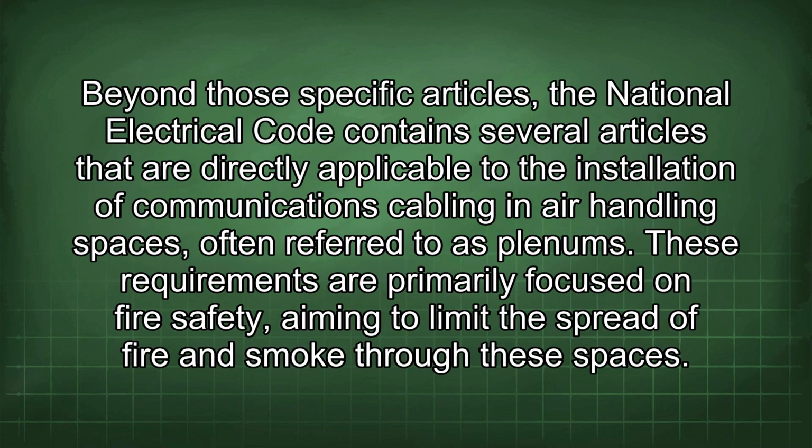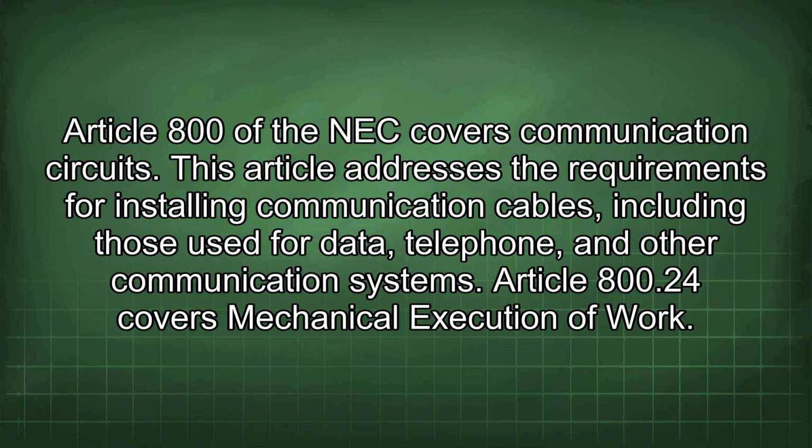Beyond those specific articles, the National Electrical Code contains several articles that are directly applicable to the installation of communications cabling in air handling spaces, often referred to as plenums. These requirements are primarily focused on fire safety, aiming to limit the spread of fire and smoke through these spaces. Article 800 of the NEC covers communication circuits. This article addresses the requirements for installing communication cables, including those used for data, telephone, and other communication systems.